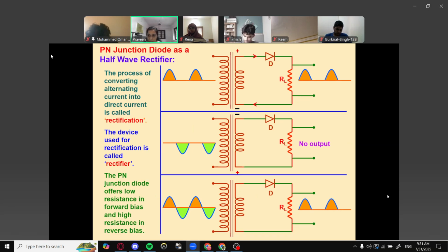Now listen to me very carefully. I told you for AC, you have positive half cycles and negative half cycles. When you apply an AC signal to a diode, suppose first the positive cycle is fed to the diode. So the diode has a positive to positive connection. So it is forward bias. So the diode will be conducting.